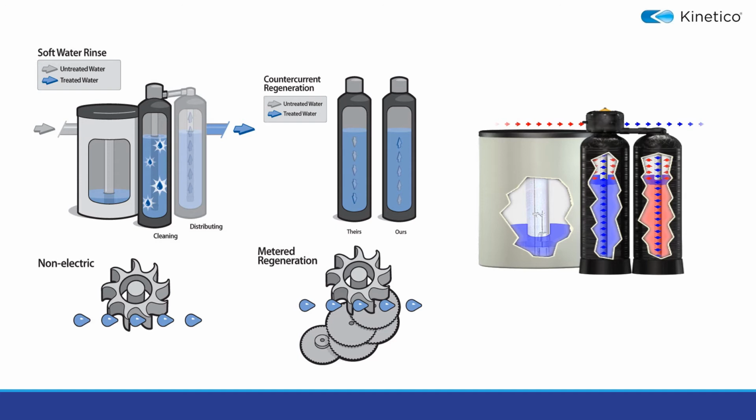The first diagram I want to show you is on the left, and it's a twin tank softener. And what you'll currently see is that the system is in regeneration, and you'll see here that it's cleaning. But you'll also see that the system is in operation. So hard water is entering the unit and serving soft water to the home. This allows for peace of mind of 24/7 treated water, regardless of the usage. These tanks will alternate back and forth as needed.